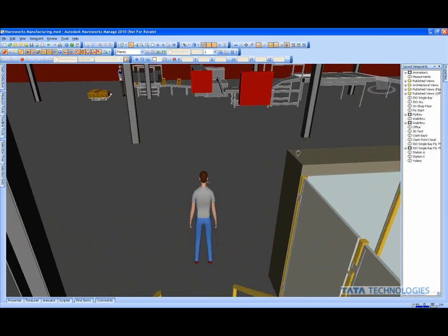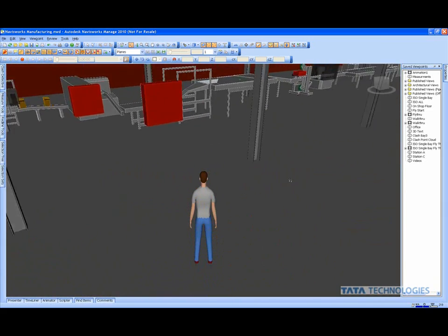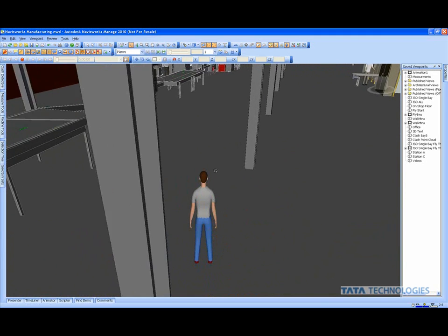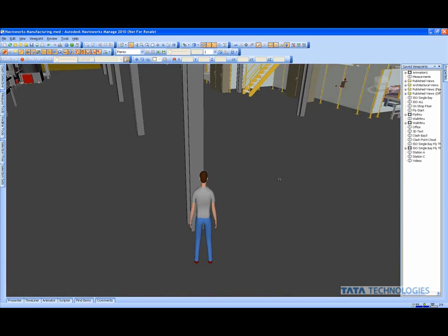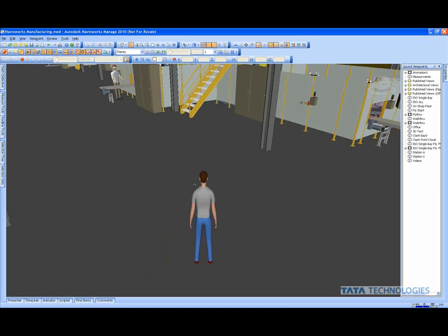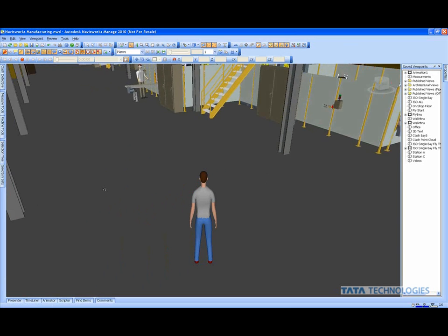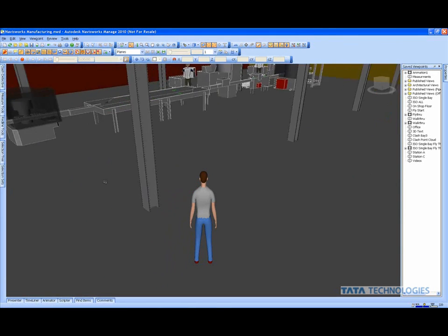Some other things we have is the ability for clash detection. With clash detection on, that means he bumps out of the way of items. So just some simple things as we're walking through can really be handled. Gravity, collision. You want him to crouch if he gets to an object that's too low. So I've turned off clash detection, which means I can walk right through things.